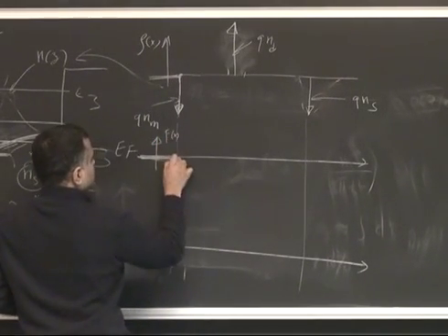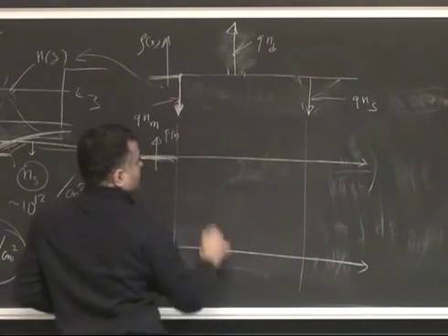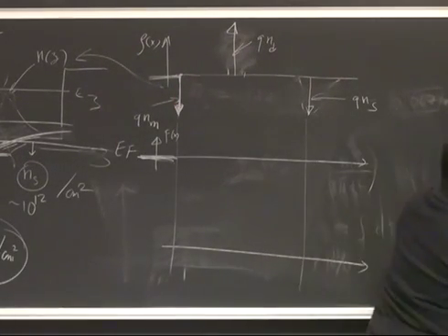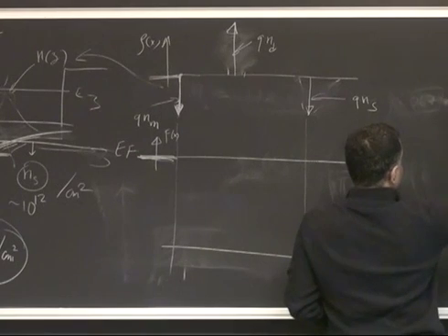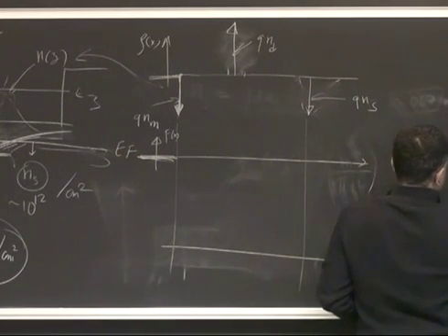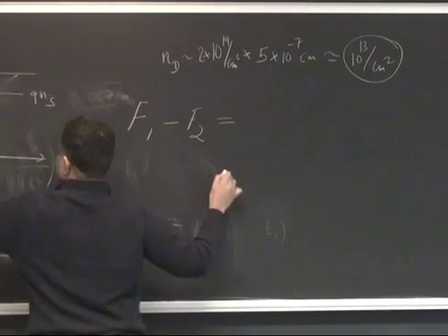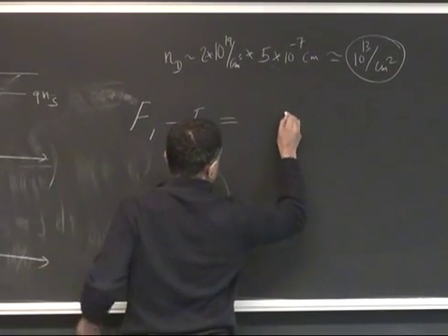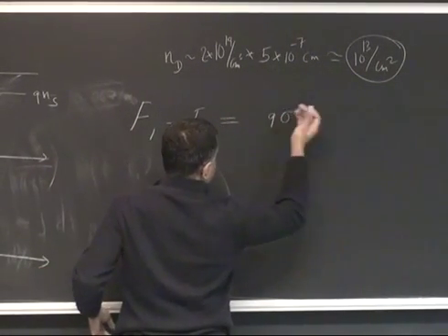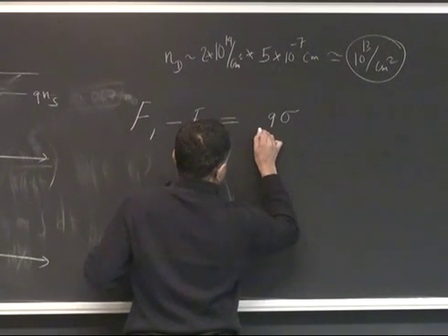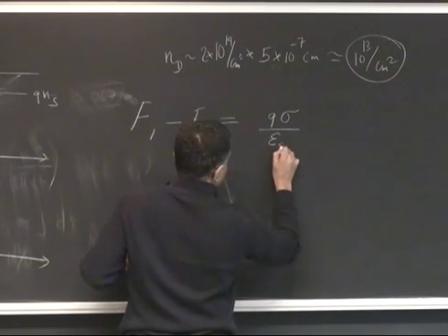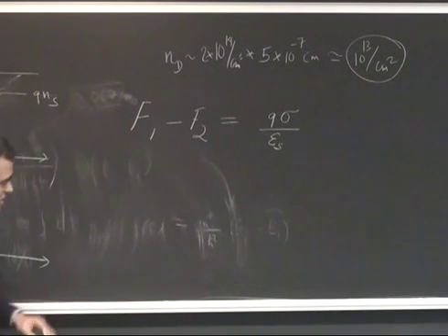The field is 0. Then you hit a sheet charge, and I think I did mention it when we were doing p-n junctions, but I'll mention it again. The field discontinuity across any region which has a sheet charge, let's say sigma, Q times sigma is the sheet charge density, is just that divided by the dielectric constant of the insulator part of it.